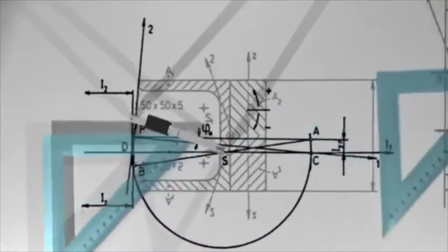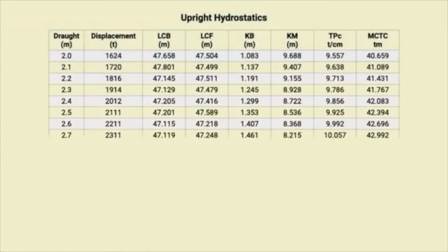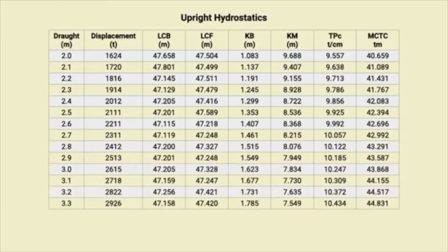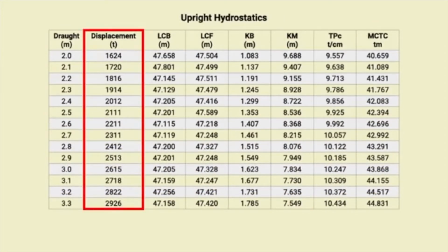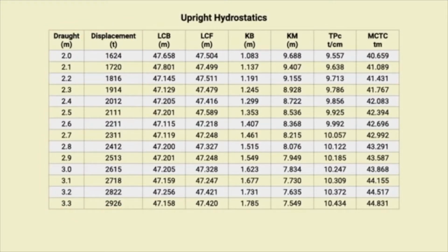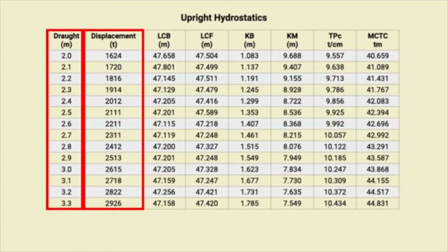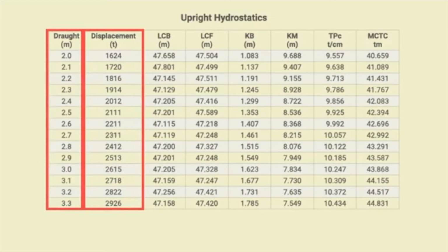Ships and boats are designed by naval architects who model the exact shape of the hull. They give us a set of tables that we use to work out how much cargo a ship can safely carry. For different weights, these tables tell us how low she will sit in the water. Now the beauty of maths is that it works both ways. Instead of working out how low she will sit for a given weight of cargo, we can work out the weight from how low she is sitting. So how do you know how low a ship is sitting in the water?